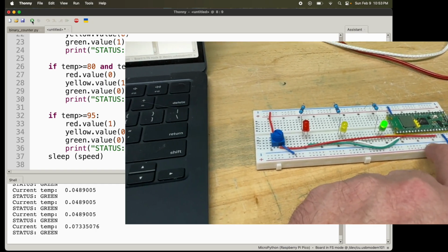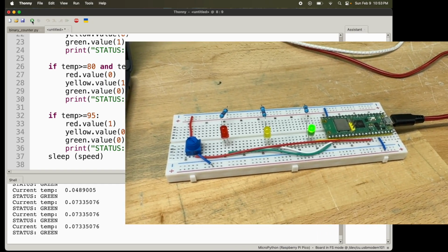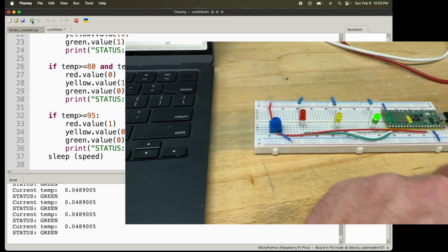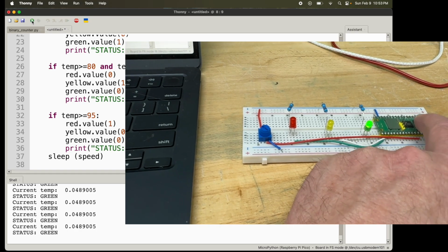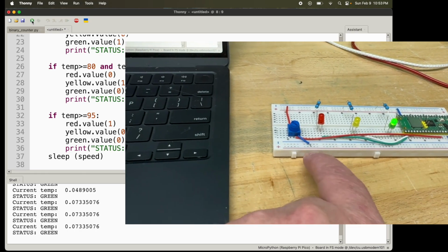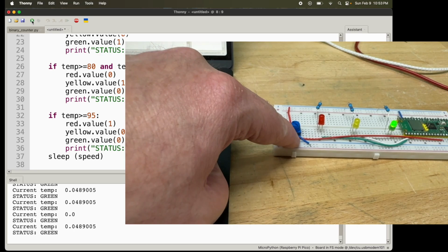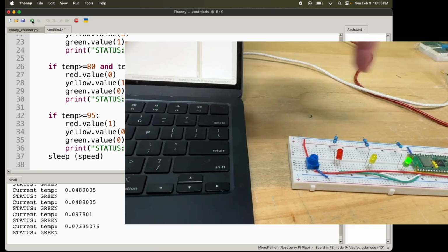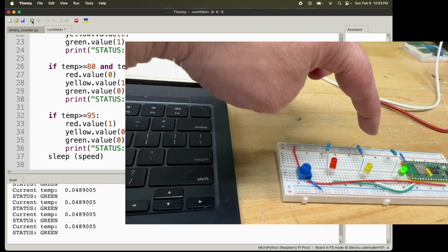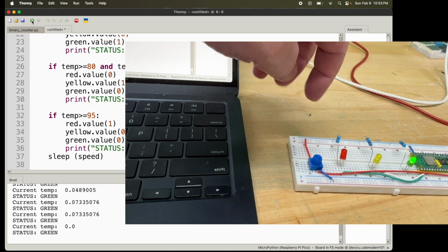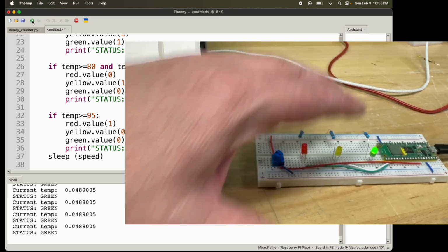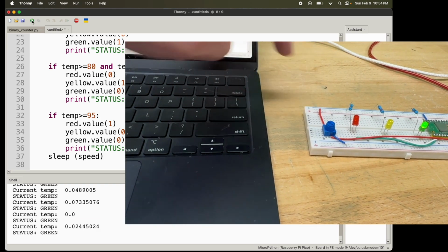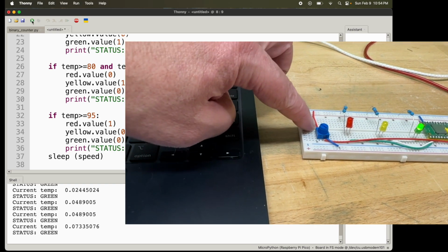But this is a fun one because you have a lot of components on the breadboard and you really have to think about how you're going to route it. So like I have the 3.3 volts on this side of the board. So I tied into this rail here and then brought the voltage in right there. And then I already had a ground set up over here for all of my current limiting resistors to tie into. I wanted my resistors back away, kind of out of the way. So I used the ground line right here, and then I also tied the potentiometer in there.